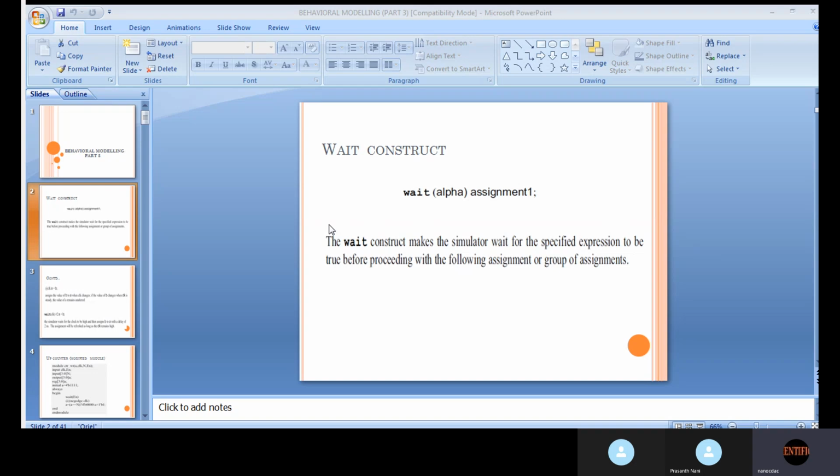When instantiating, if we give vectors, it is not getting executed. Earlier also you asked me the same thing, and when we instantiate nor and not gates, these things are not working out. Instantiation is taking only a 1-bit vector.